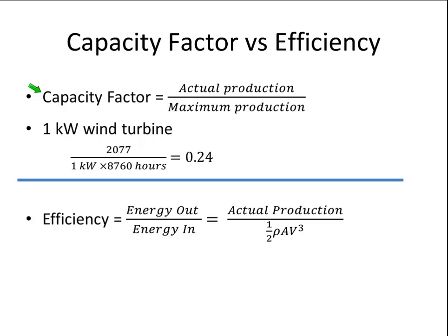If you broke down, that's going to make you run less of the year, thus you're going to have a lower capacity factor. We're seeing some of the new wind farms that are put up in Nebraska in some very good locations, in their first part of the year that they're running, have capacity factors in the 60% range, which is phenomenal. Part of that is they're brand new, so they're not breaking down, they're functioning very well, but also they're being put in a place that has very high and consistent wind speeds.